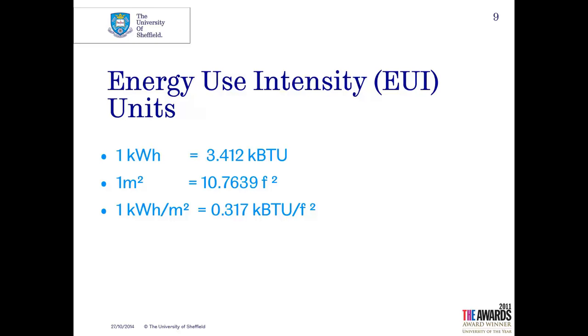If you're looking at a project in America, they may well give you the figure in kilo British thermal units per square feet. And it's handy just to have that conversion factor in your head so you can compare. Equally, when you're looking at projects in Europe, more and more journals, more and more architectural books now will actually give you the energy use intensity of that building. And that's hugely important because you can immediately make that comparison in terms of performance.